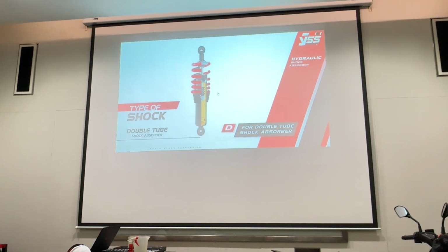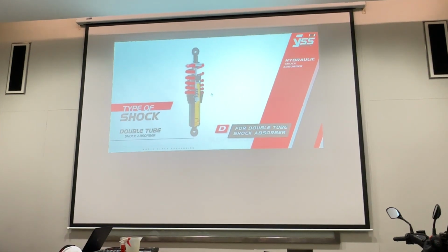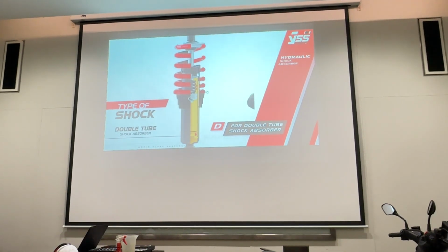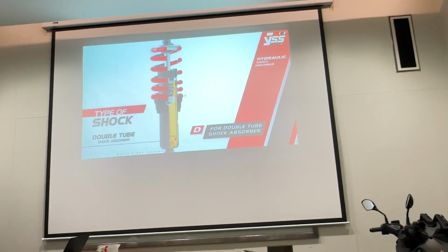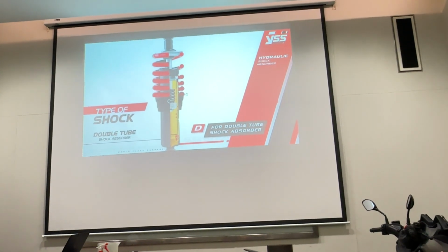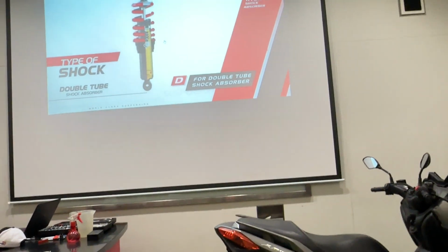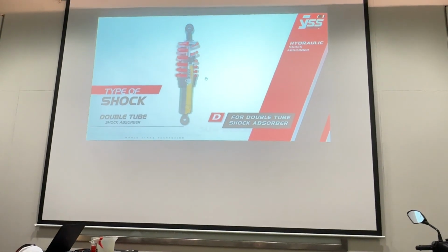Double tube or D. This shock absorber has double tube. The advantages are smooth ride, durable and safe from crashing. It works with piston moving through the inner tube. Hydraulic oil flows through base valve, which works together with piston set. However, its ventilation system is slower than single tube shock absorber, and the price is higher. Plus, it has to be installed shaft at the top.